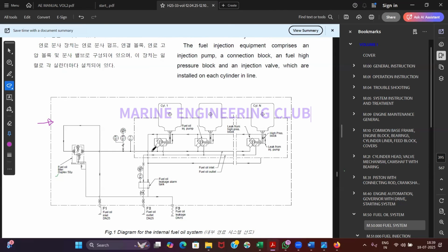और सर ऑक्सिलरी में? In the auxiliary engine, what you can do is, first of all, we will not do it, but आप उसका रैक खींच लो बाहर, रैक डिस्कनेक्ट कर दो, जीरो पे ले आओ. बट रैक तो सर सारी रॉड का एक साथ कनेक्टेड रहता है ना, पूरी रॉड मूव करेगी सर? No, you can remove the single connection itself. Remove the connection and pull it. सर, उसको बांध के रख दो वहां पे. बट दैट इज नॉट डन ना. एक कट ऑफ करके हम जनरेटर को नहीं चलाते हैं. यस, मेन इंजन वी कैन रन बट नॉट जनरेटर.